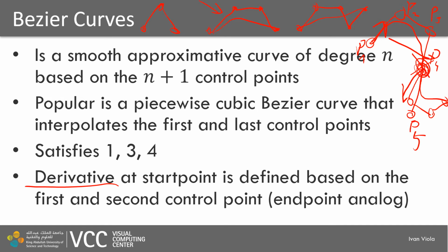Then we have the C1 continuity. If only the orientation is secured, but P5 is a little bit further away, then we have the G1 continuity. And if we place the point P2 and the point P6 in suitable positions, then we can secure the C2 continuity, so that the curvatures at the point P4 are the same from both sides.